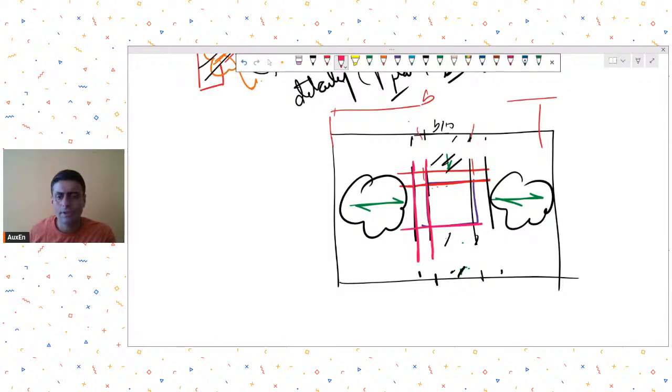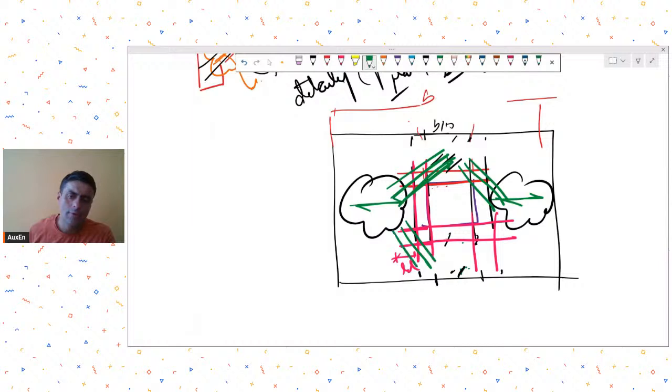You could refer to SP34, and then you could just continue the reinforcement of these till LD, and also you provide diagonal 3 bars at top, 3 bars at bottom, diagonal bars, and continue it till LD like this. Okay, so this can be a typical reinforcement arrangement provided in the vicinity of openings.